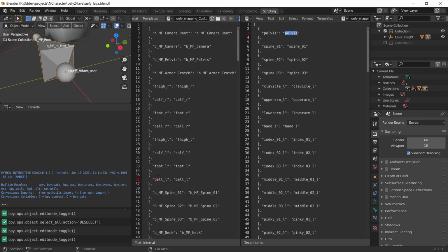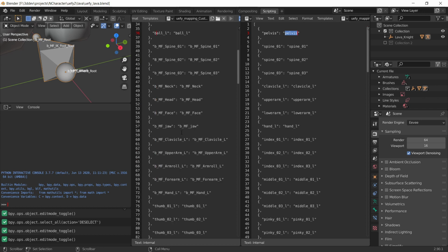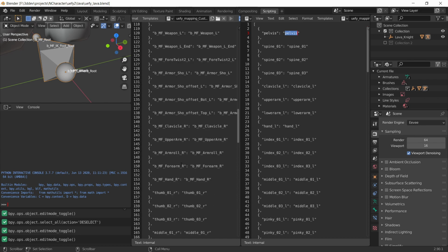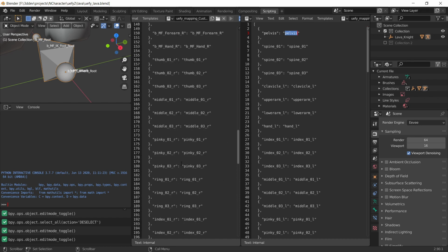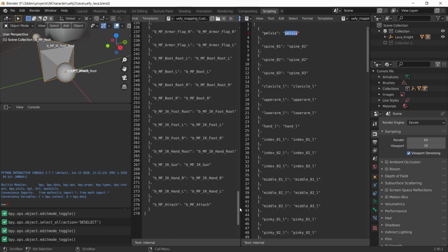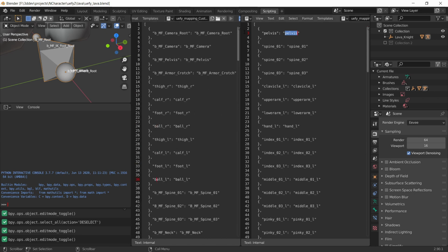So any name that is already correct is something that I don't have to fix. So all of the fingers are fixed, so I don't have to do any of this copy pasting. And the only thing that is left for me to do is fix the spine and the 4 bones in each of the arms, because well, the bone rename tool fixed the legs as well. Now I can start at the top of this column and then just go down one by one. And I'm only interested in bones that exist in the Unreal Engine Mannequin.